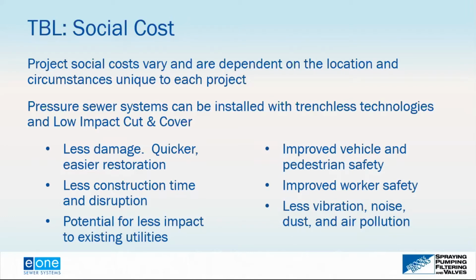If you're in an area that has a lot of utilities, a gravity sewer system will, maybe I shouldn't say always, but in most cases will be the lowest utility in a utility corridor. So if you're going into an area with existing gas mains, fiber optics, water lines, any other kind of buried utility, with the gravity sewer system, you have to work around that while also maintaining that constant slope. So there might be cases where a gravity sewer system would have to be installed at a deeper excavation just to avoid a water line or just to avoid a gas line.